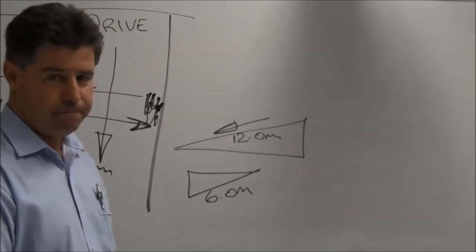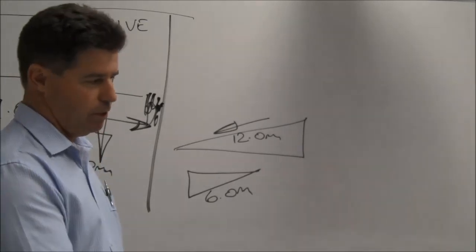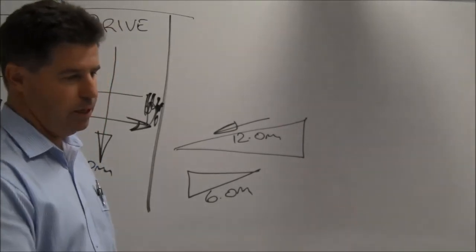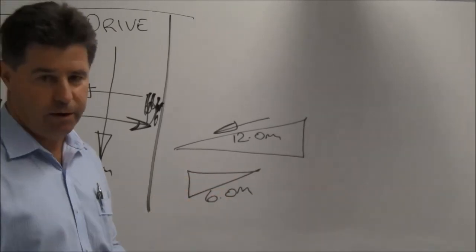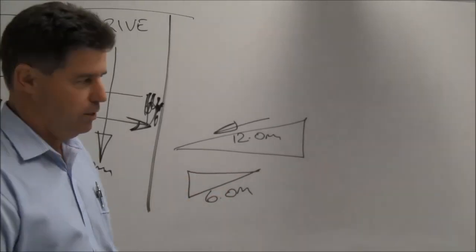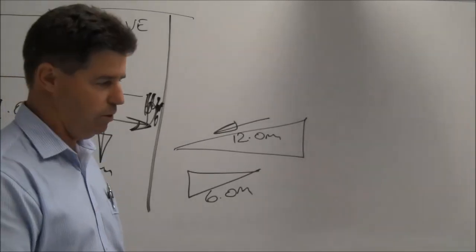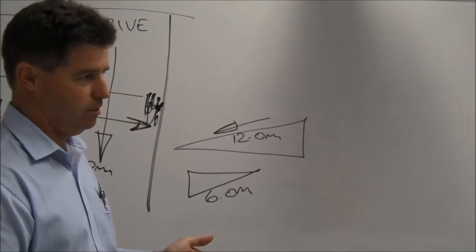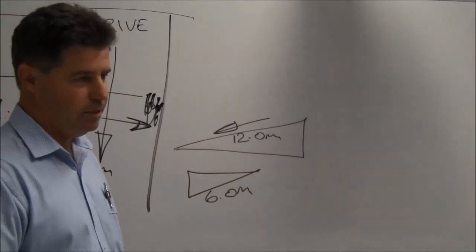So you're exposing them to more than what they're getting in 3500. Well, 3500 doesn't have any equations. It just has a graph that says you must fall within this area. If you go outside of that area, what do you do? You need some tools. So if you go outside that area, then people need to say, well, sorry, Mr. Architect, I can't give you that, I've got to give you more downpipes. Well, that's not the case.